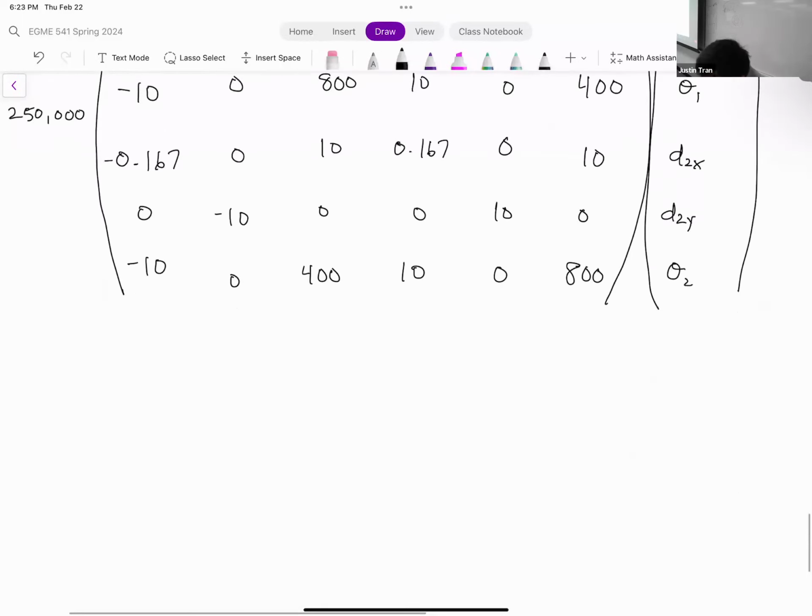So let's go ahead and move on to element B. Element B is our horizontal element that's on the top of the structure. So for element B, let's write out the angle. Our angle here is 0 degrees, because it's a horizontal element. Based on that, we know cosine of the angle is 1, sine of the angle is 0.